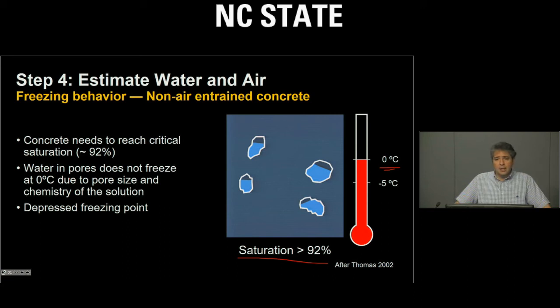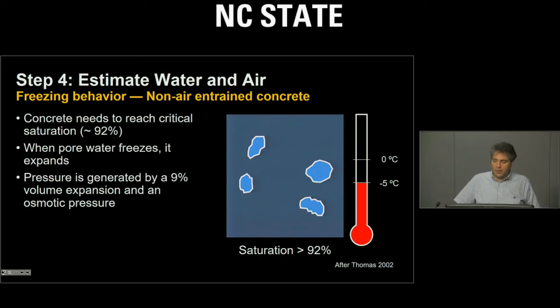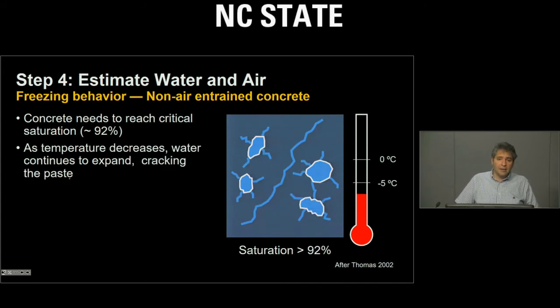These effects depress the freezing point. Now, if we have a concrete that has a degree of saturation of 92%, concrete that has been exposed to a lot of water and has been saturated above 92%, when the temperature drops down, the ice will start to form inside the system and will start to expand, and will result in cracking of the concrete.